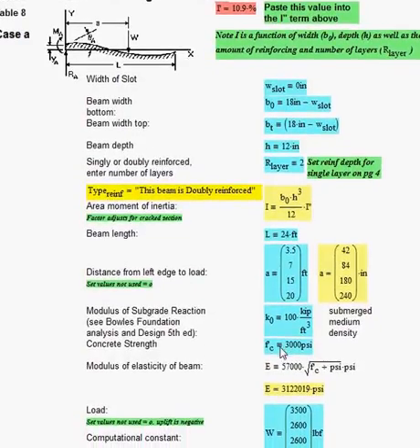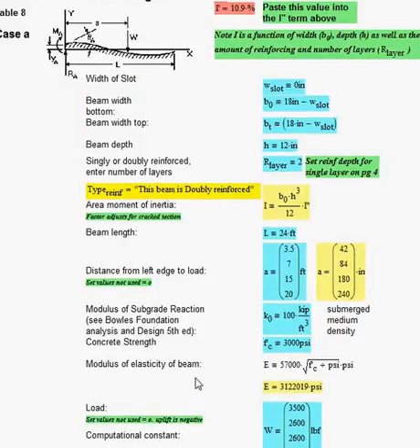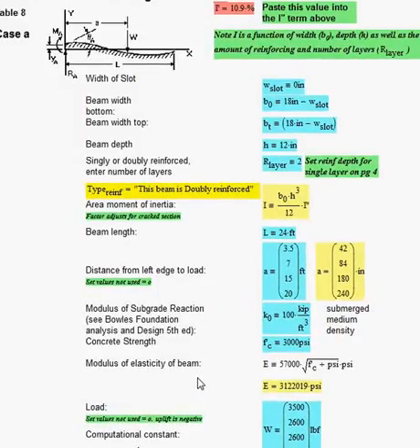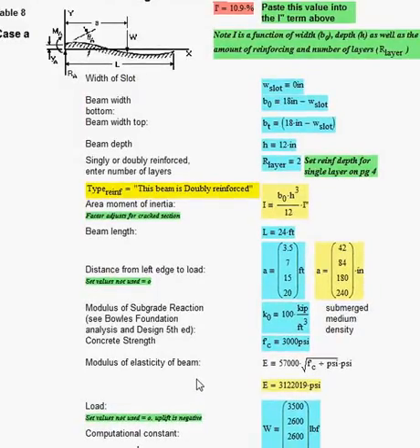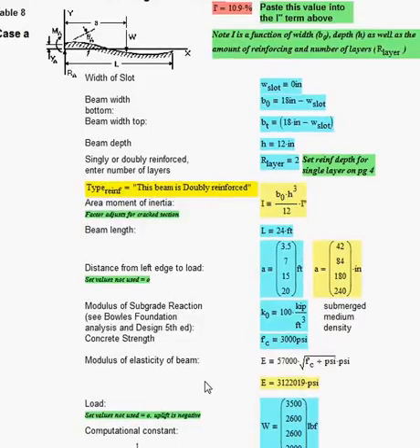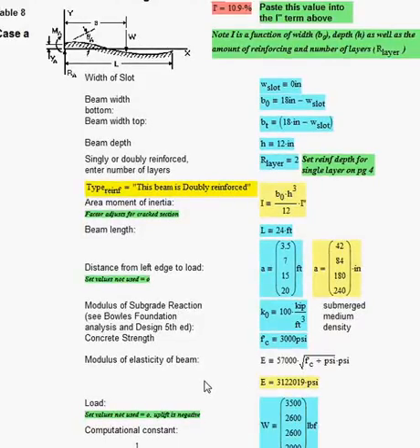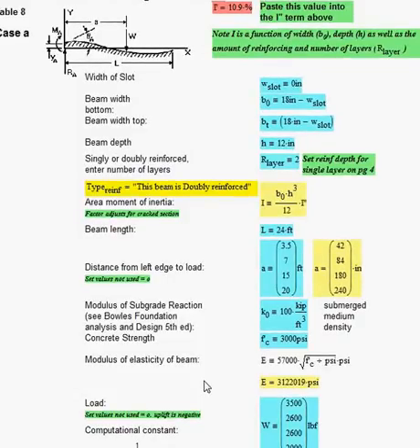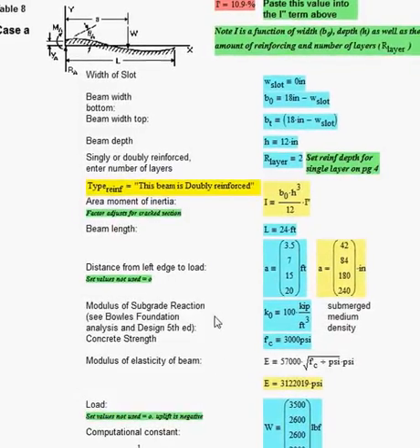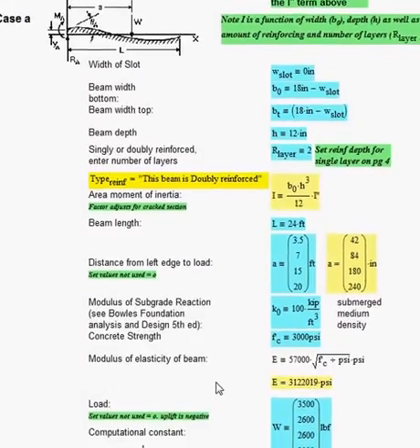The modulus of subgrade reaction is input, and this should be based on the site-specific soil report. Outside the margin, there is a discussion to help select a correct subgrade modulus that may be used as a guide, but the user is responsible to specify the correct value based on site-specific information.